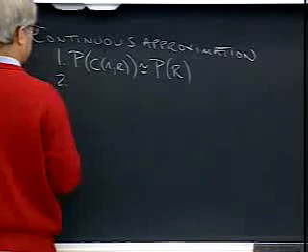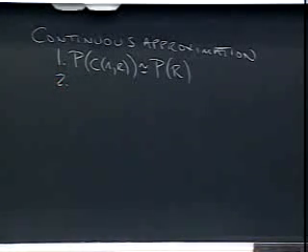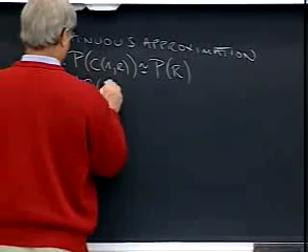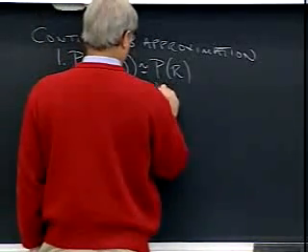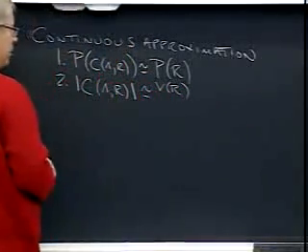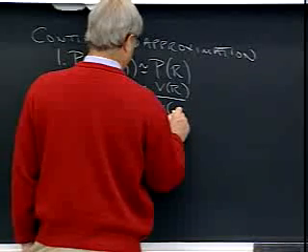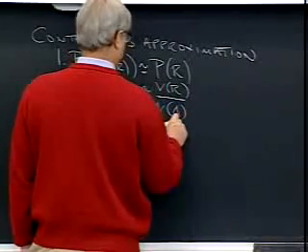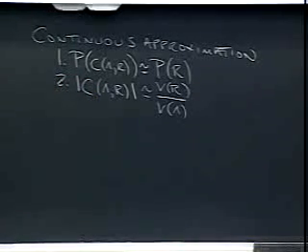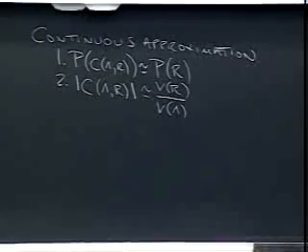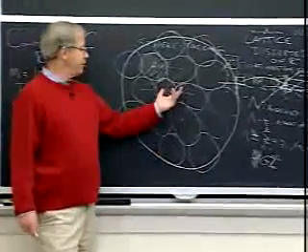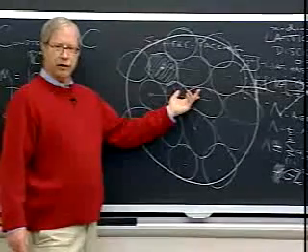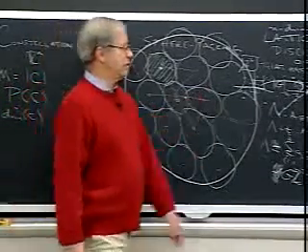And then I'm going to say, furthermore, how many points are there in the constellation? This will affect what rate I can go at. The average number of points in the constellation is going to be approximately equal to simply the volume of my bounding region, V of R, over the volume taken up by each point in my lattice. Okay, that makes sense, doesn't it? What I want to do here to get 16 points is I take a sphere whose area is roughly 16 times the area of one of these little hexagons or one of these little parallelograms, and I'll get about 16 points because that's the density of it.